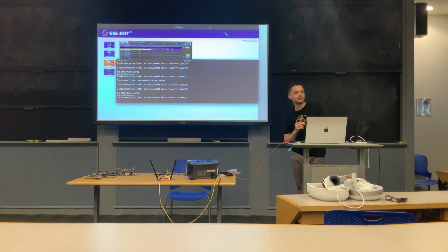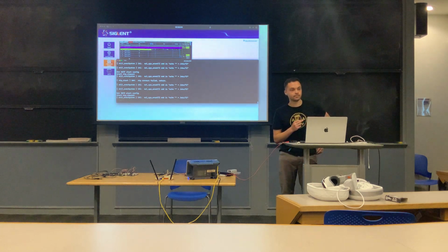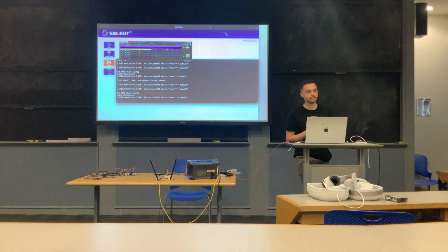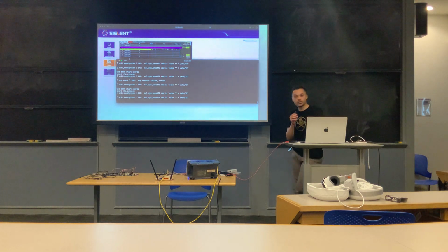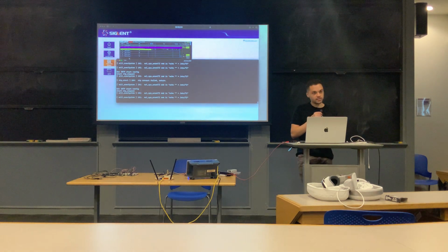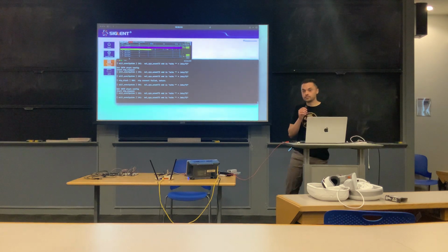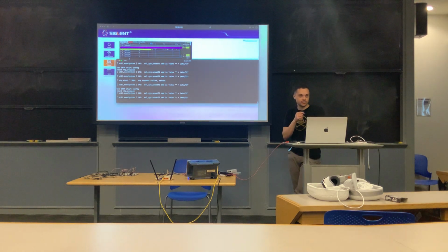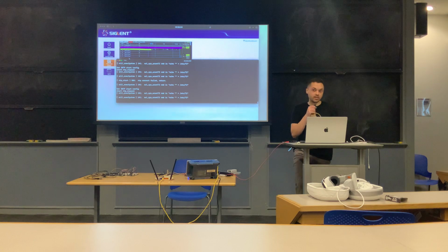What if the OS is not a Linux that we can use this to talk to, or the protocol is not a well-known one that we can just guess? Excellent question. So in this case, we were able to just guess the protocol. Like I said, it's a very common protocol, so I was able to guess. If you didn't know what the protocol was, you'd have to do more reverse engineering. But you'll find, I'd say 9 times out of 10, it's going to be this type of 8N1 encoding on UART. So let's talk about UART.